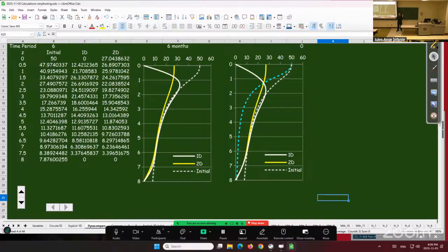Okay, so in terms of width, they're both the same dimension, right? They have the same diameter. And the circular one is smaller than the square one. Yes, the circular one is finite perpendicular to the plane, right? It's finite, so the stress, because it distributes laterally, it adds up, so the points that are over in the distance, they add stresses here, so you should expect the strip footing to be larger at any depth. Except right under the load. See, right under the loaded area, they're exactly the same value, 50 kPa.